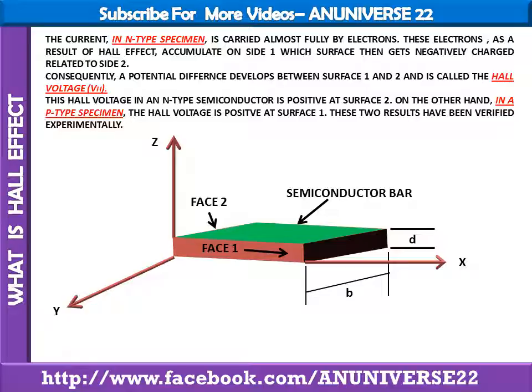Generally the Hall effect may be used for determining whether a semiconductor is N-type or P-type, determining the carrier concentration, and calculating the mobility having measured the conductivity. The Hall voltage VH for a given current is proportional to B, that is the magnetic field. Hence measurement of VH measures the magnetic field, and it is also a Hall effect multiplier.